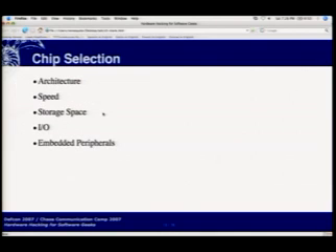A few notes on architecture. With a lot of the smaller microcontrollers, you have your choice between 4-bit, 8-bit, 16-bit, and 32-bit. Now, the biggest difference between these, other than register width, is cost. And a lot of it is also speed of the processors. With a lot of the lower end 16 and 8-bit stuff, you're going to max out around 40 megahertz, and your onboard flash and RAM is going to be less than a meg combined.